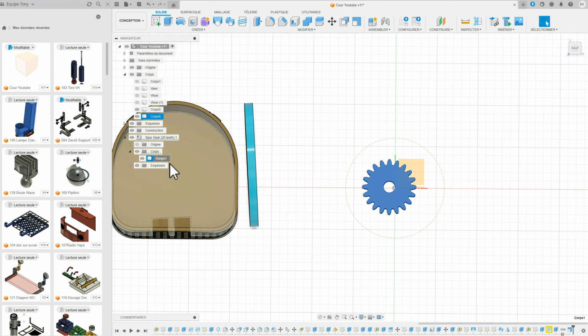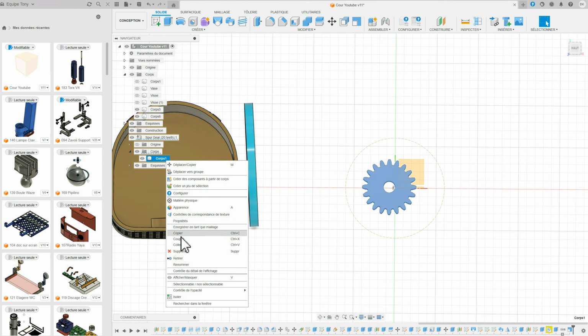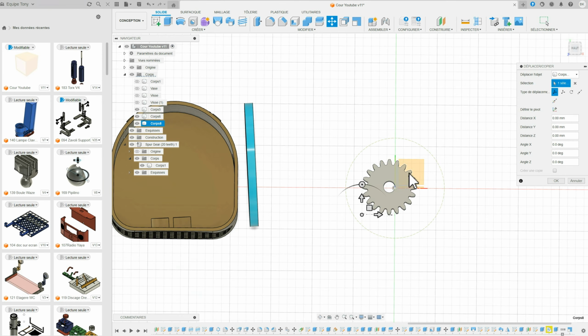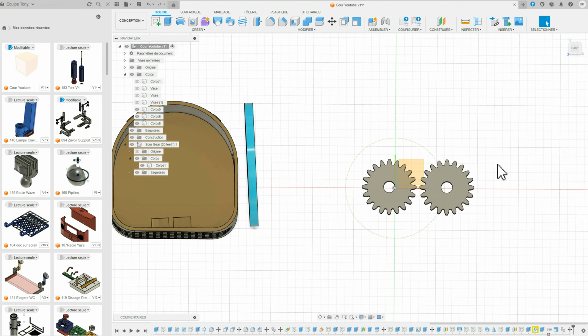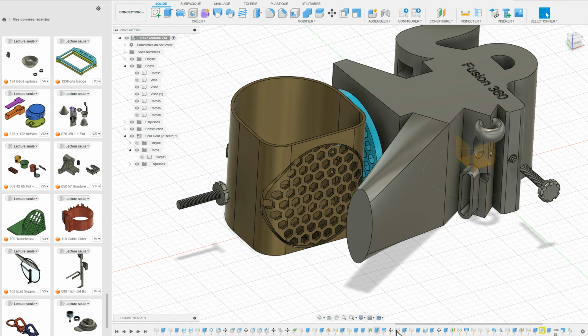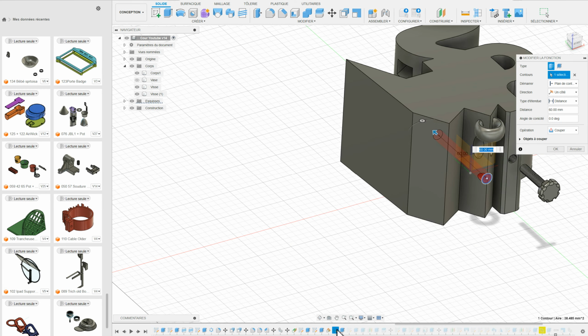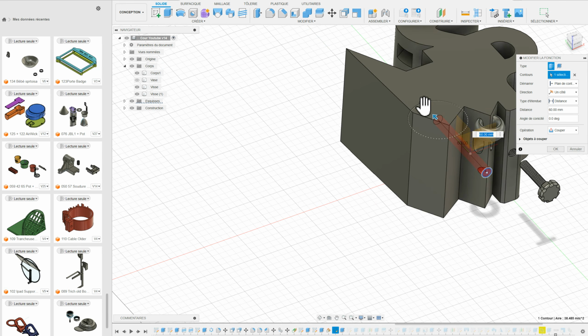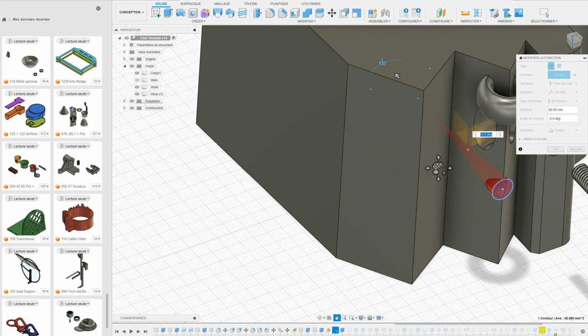We're almost at the end of the tutorial, yet there are still loads of tools and options, forms, technical drawings, electronics, but we won't have time to cover them, and I don't know them that well anyway. Before finishing, I want a tool and two options. Right-click here on the hole and modify it. If I tilt the part a bit, you'll see a small circle. If you move it to the right, the hole gets bigger. To the left, it gets smaller.